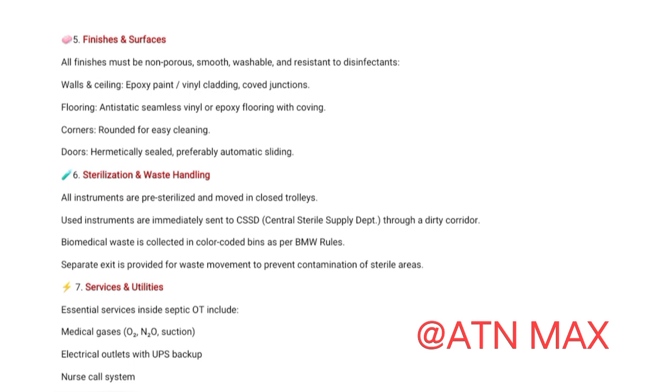Finishes and surfaces. All finishes must be non-porous, smooth, washable, and resistant to disinfectants. Walls and ceiling: epoxy paint or vinyl cladding, with cove junctions. Flooring: anti-static seamless vinyl or epoxy flooring with coving. Corners: rounded for easy cleaning. Doors: hermetically sealed, preferably automatic sliding.